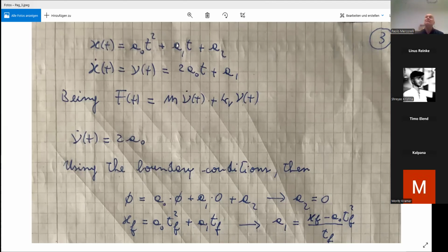What happens if I consider the polynomial of order 3 in this context here with just two conditions, because initial position, final position, and of course, time. The time is implicit in the sense. We will end up, nevertheless, in the polynomial of second order. This could be nice also in a possible project. I mean, if I add t up to 3, multiplied by a constant, this constant will be automatically calculated as 0, if the conditions are true. Of course, I can include another condition if I have a polynomial of order 3.